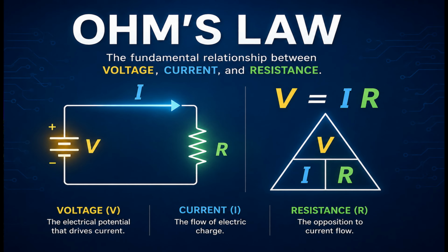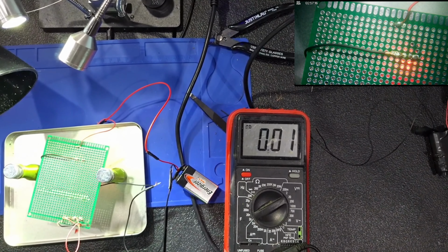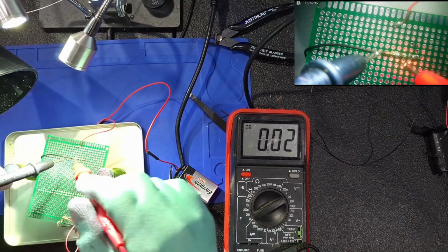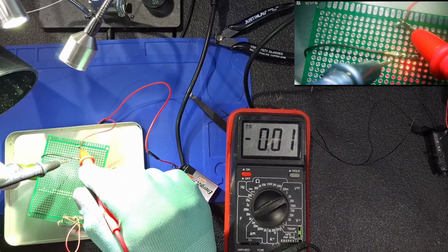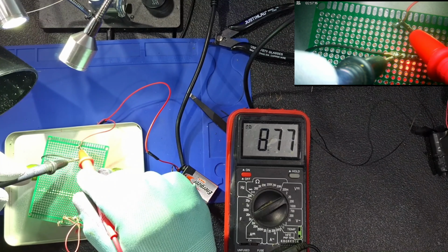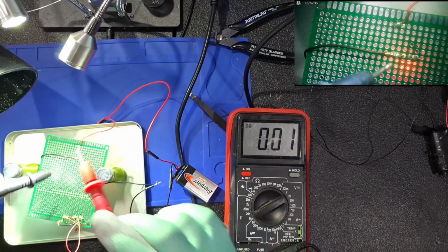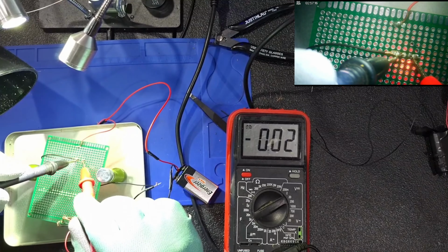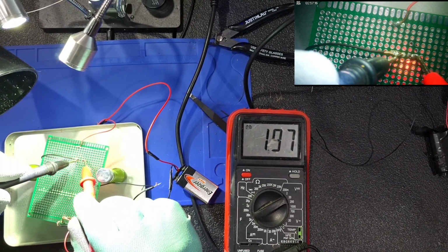Okay, I guess it's safe to say I understand voltage, current, and Ohm's law so far, but I need to understand how to measure current. And what I found out lately is that measuring current is not the same as measuring voltage. Because measuring voltage, you have the black probe, the red probe, red to positive, black to negative, put it on the DC volt and you measure. That's not how you do it with current.